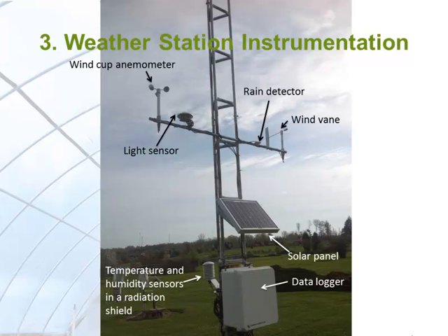Did you find something that needs improvement on this weather station? It is a big challenge to notice anything wrong with this weather station without knowing its orientation. As mentioned earlier, this weather station is located in Ohio, where the sun is always in the southern half of the sky. Thus, it is reasonable to assume that the solar panel is facing south. With that established, we find the light sensor is mounted on the west side of the tower, and the wind cup anemometer is mounted further west of the light sensor.